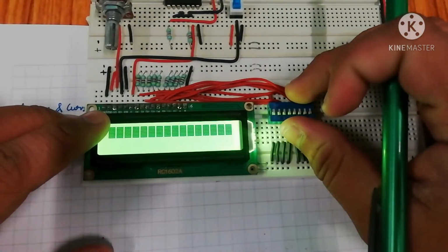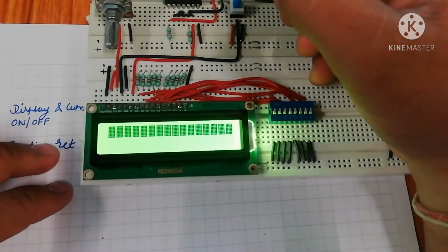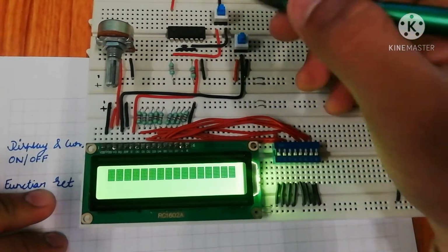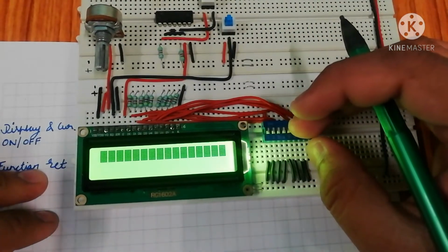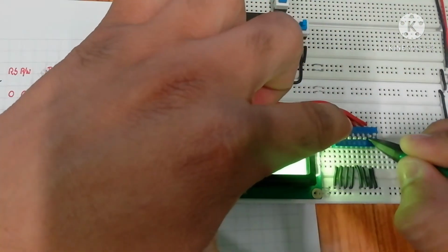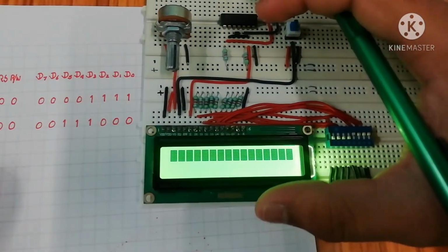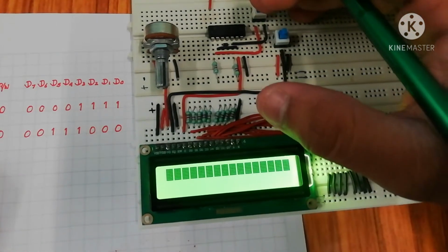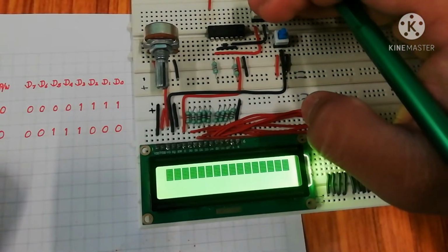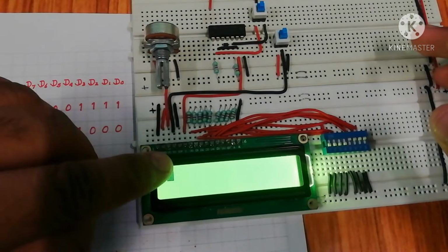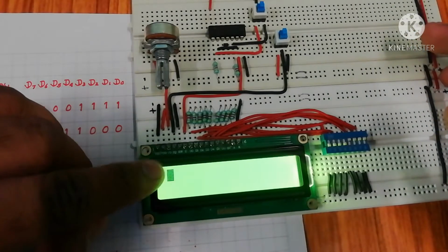We issue these commands through these 8 dip switches. Now the register select pin is connected to ground, which means the given command is an instruction, not a character. Let's set the dip switches in the desired manner and observe what happens. Looking at the opcode, now the enable pin comes into play. The LCD reads or writes data by setting the enable pin to logic 0. Let's set the enable pin to logic 0 and observe what happens. Adjusting the contrast, as you can see this puts a blinking cursor on the top left corner of the LCD.